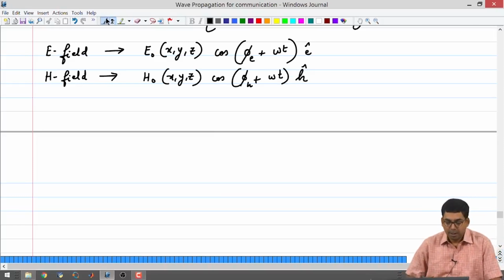If you were to calculate the power density directly by using E cross H is equal to P, our understanding is that that is also going to depend on time. So, let us first start with the simple calculation for power density, and since this is instantaneous electric field and instantaneous magnetic field that we are using, the power that we are calculating will be known as instantaneous power, or instantaneous power density, if you wish to call it.